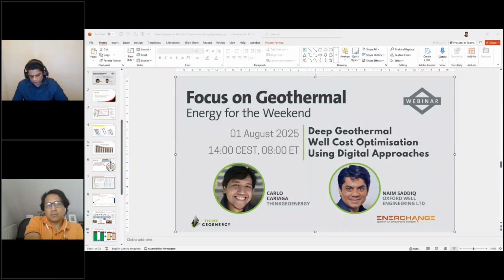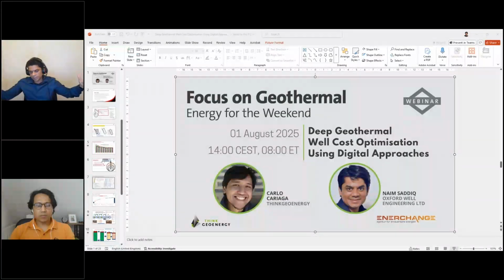For geothermal wells, it comes from the way that the rig does things, the rig operations, how it makes connections, how the day crew works, how the night crew works. Sometimes there's a big difference between the night crews and the day crews. One crew is doing it in certain ways. The most important word I want to say about invisible lost time is the consistency of the operation. How consistent the connection time is, for example, 3 minutes, or sometimes it goes from 3 minutes to 20 minutes. If nobody sees them, they will not be like a bell-shaped curve. They are spread out and very inconsistent.